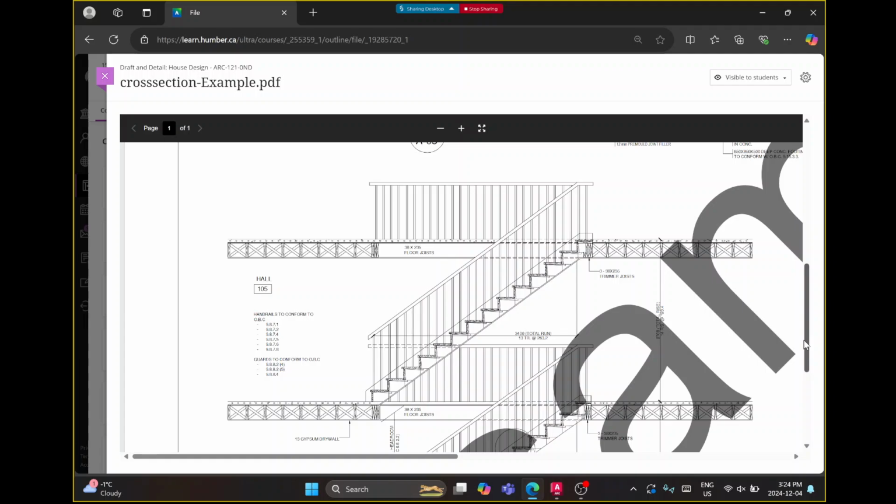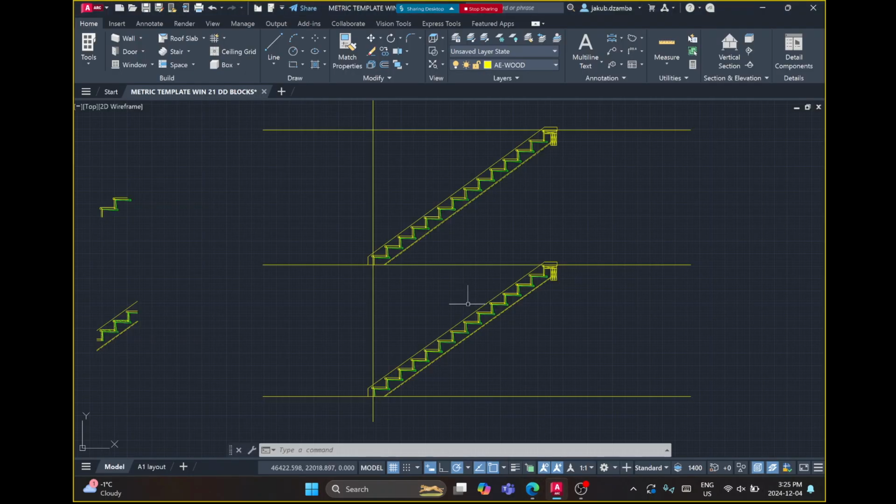The last thing we need is the railing, and it's actually quite an easy thing to do. Really, all we're going to do to get the railing, we offset this line up 1,000. Offset it down 70, that's the width we chose for our railing, and we simply connect it with pickets. The best way to do it would be to set it up so that we land 2 on every stair, and you just copy it all the way through. I can show you how to do that really quickly as the last step, and I think that lets you finish the drawing. So, this is how I would do it.